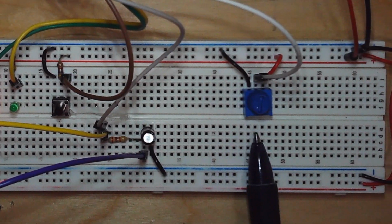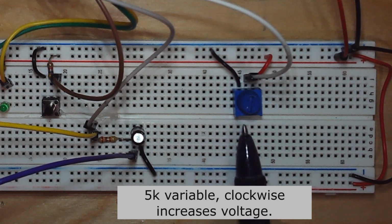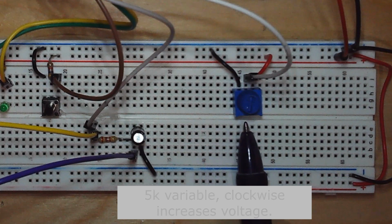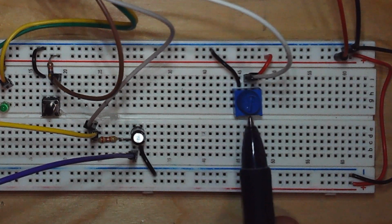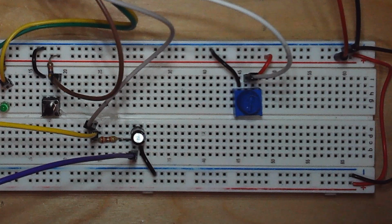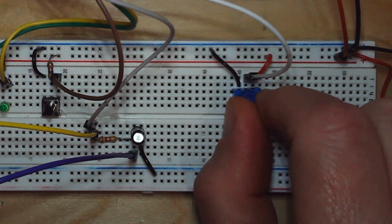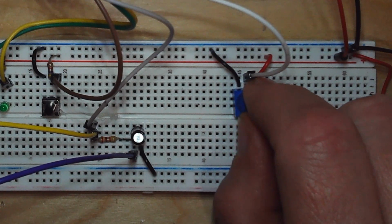Further over here on the right, we have the variable resistor. This variable resistor is going to adjust the output voltage somewhere between 0 and the supply. Nominally, the supply is 5 volts, but that could be a little bit less. In my case, it's 4.75. So if I turn it counterclockwise, it will reduce the pulse width modulation output all the way down to 0.